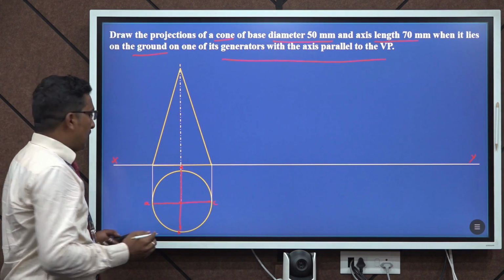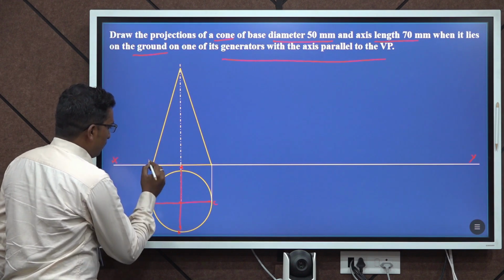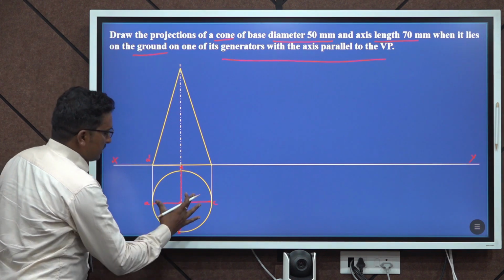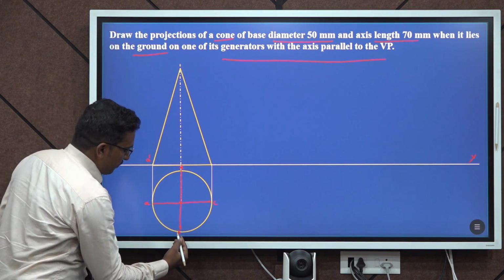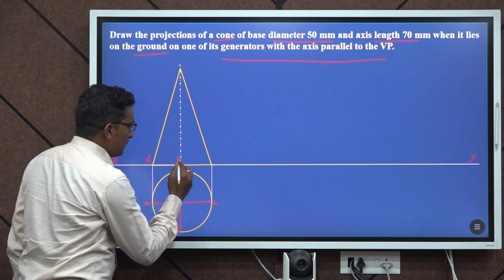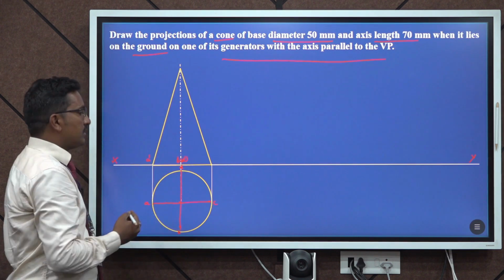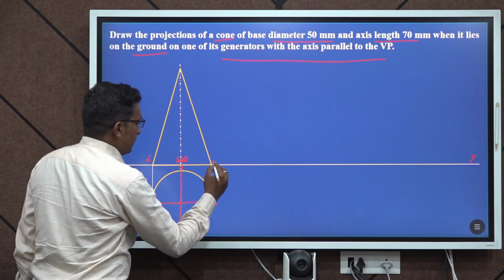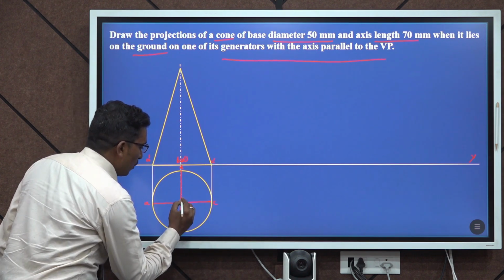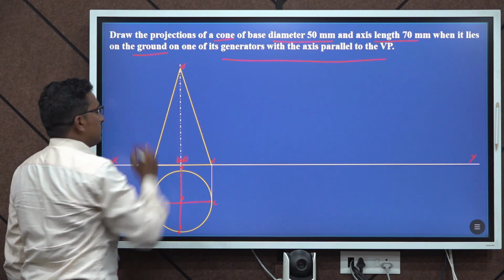Now I am going to give the names in the front view. While seeing the circle from the bottom, first of all you will see B, hence I have given the name B dash, and then D is hidden, hence I have given it in brackets, and then C. The mid of the cone is O, in the front view presented as O dash.